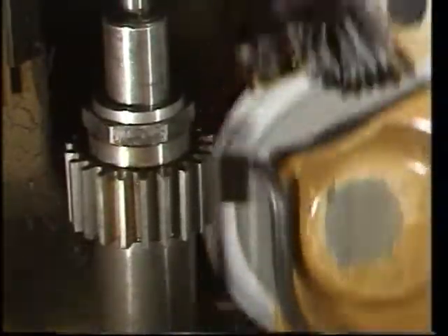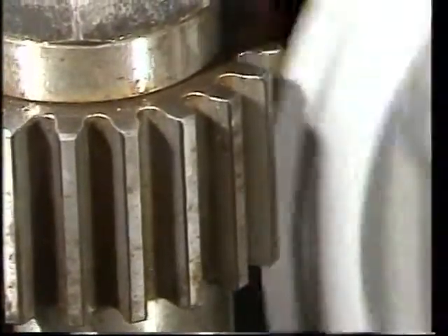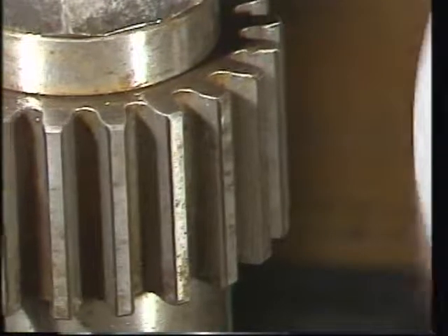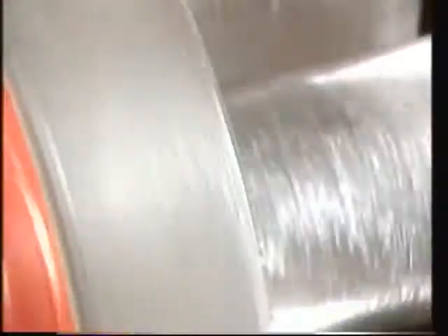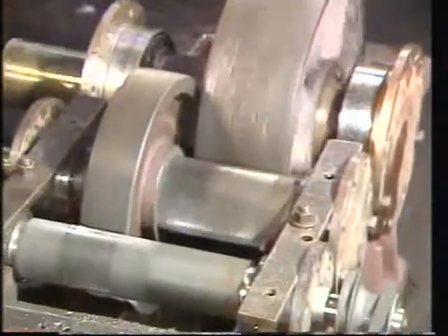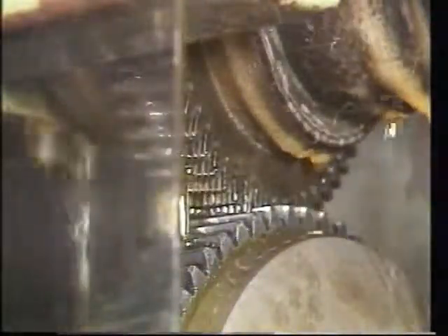Spur gear teeth are subjected to finishing operations in specific cases where high accuracy is required, especially after the gears are hardened. Grinding process produces higher quality gear finish by removing tiny flats on the surface. The other common finishing process is lapping. It involves simply running the mating gears together with abrasive paste. It improves the surface finish by removing the scales. Gear shaving is a high finishing process in lesser time. The serrated edges of the finished tool shaves off the tiny flats on the surface.